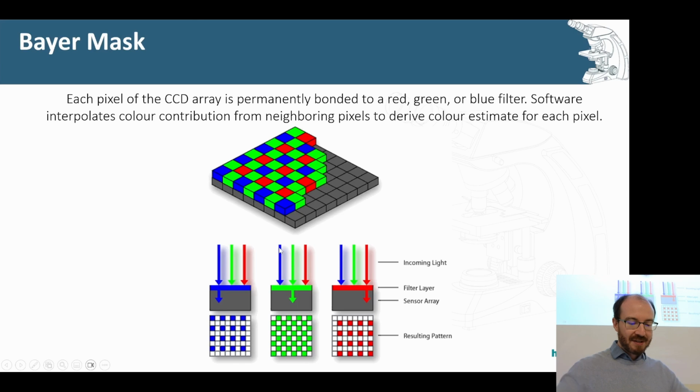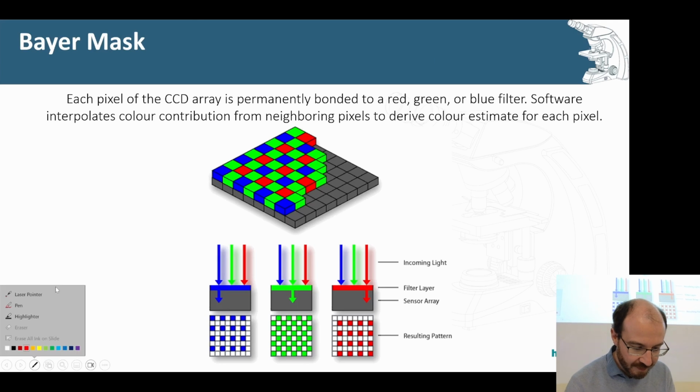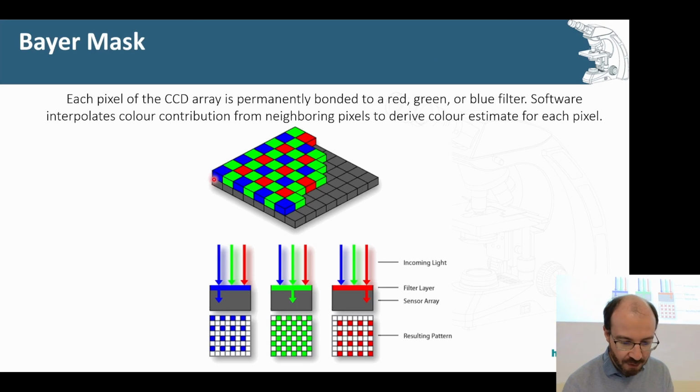You need to put them out in some kind of a grid form. So there are different layouts of these photosensitive elements that are designed in a sensor, but they're never actually exactly on top of each other. They're always put out as some grid, and then this little grid is what is associated to a single pixel. So you can now see for this one, let me just try to get the laser pointer. For this one, there are actually 4 cells there, and these 4 cells then produce a red, a green, and a blue component, which is then assigned to a single pixel.